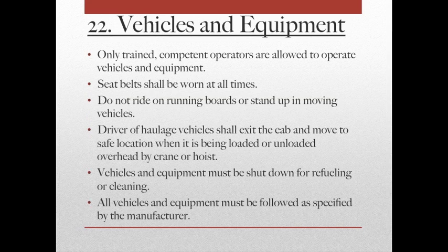Vehicles and equipment. The following rules apply while working with and around vehicles and equipment. Only trained, competent operators are allowed to operate vehicles and equipment. Seatbelts shall be worn at all times. Do not ride on running boards or stand up in moving vehicles. Drivers of haulage vehicles shall exit the cab and move to a safe location when it is being loaded or unloaded overhead by crane or hoist. Vehicles and equipment shall be operated lawfully and safely at all times. All vehicles and equipment must shut down for refueling or cleaning.